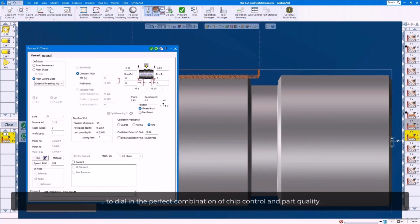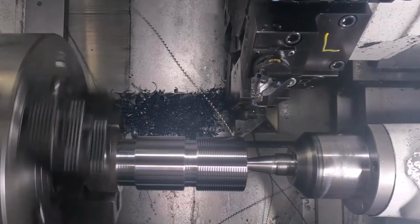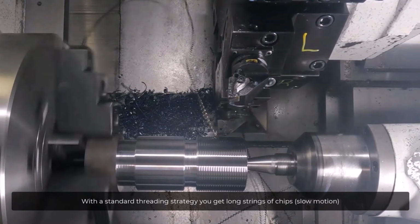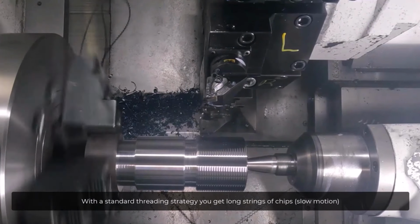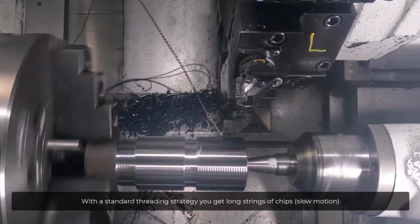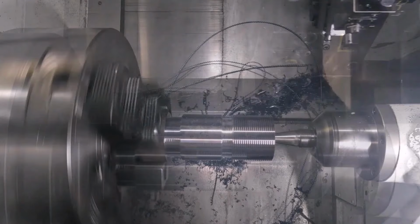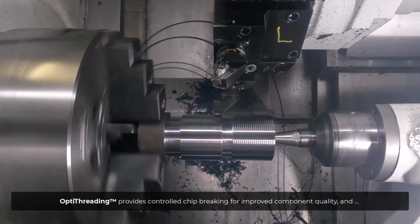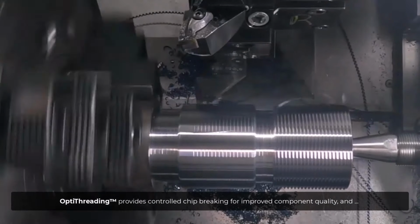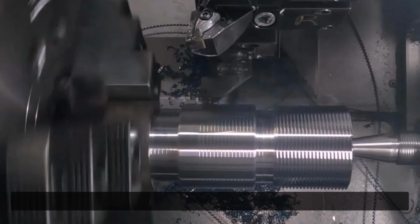And depending on where you set that oscillation frequency and even the extra lift value is how you can control how long your chip strings end up being. So here's a conventional, and here's the familiar very, very long strings of chips. And this is in comparison to the exact same thread, the exact same number of passes, but we're doing it with the oscillation of OptiThreading.